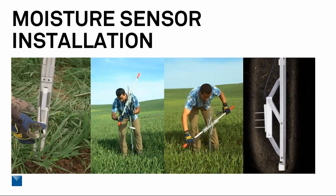Then putting the sensor in, in that first picture on the left, putting the sensor into the carriage to insert it, lowering the tool down the hole, and then finally turning the handles on top to get that perfect installation into the side of the bore hole, into undisturbed soil, and making direct measurements there. This tool helped us so much. We were able to install these sensors very, very quickly, and get in and out of the field fast.